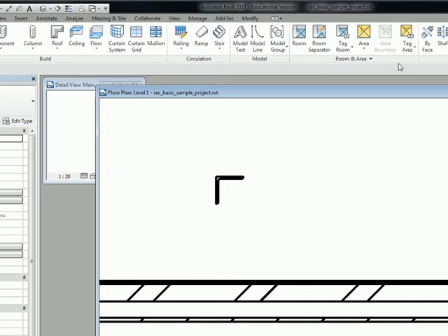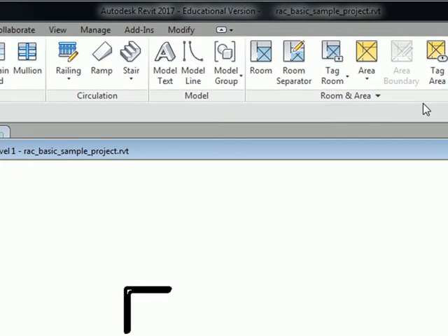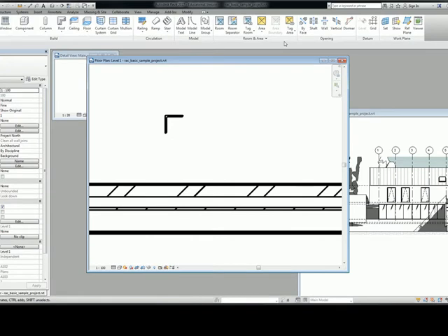So we build 4 walls and we drop a room into those 4 walls. And that room basically spills out to the maximum boundaries of those walls and creates a space. And that space, believe it or not, has parameters. And those parameters can be used to program information, like what is my floor material? What are my wall materials? What's my ceiling treatment in this space? And then you can easily put that into a schedule. Okay, so like I said, I'm not trying to teach you everything about it right now, but I want you to know where we're going and why we're going there.